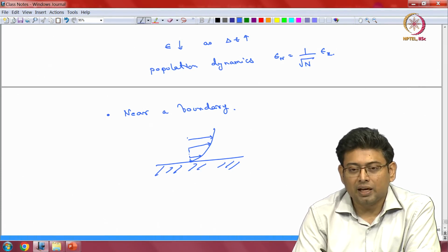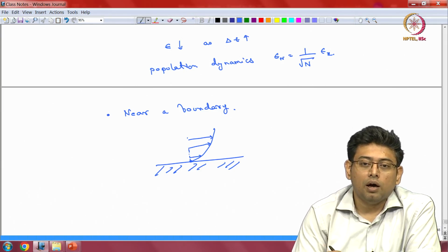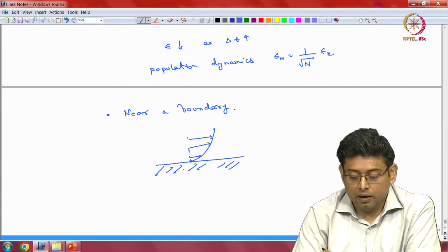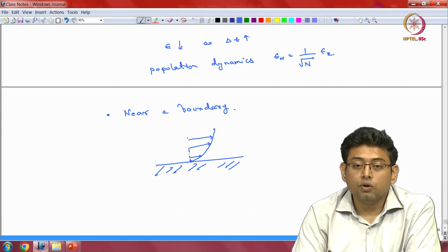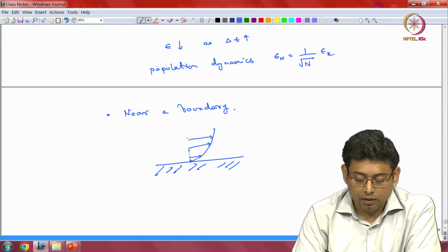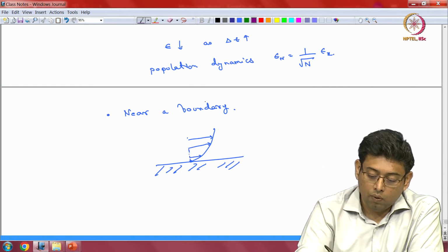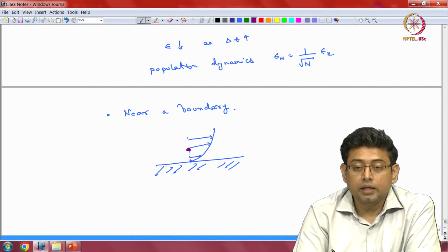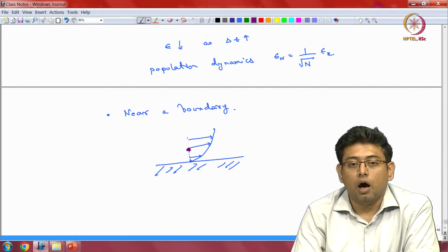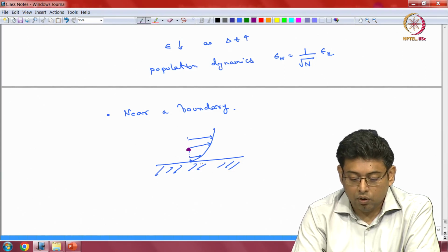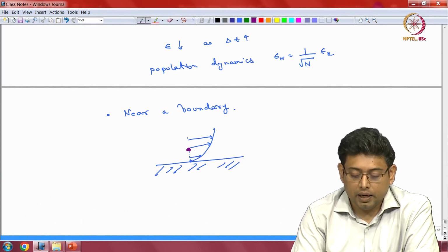This condition can be violated under certain cases. You can have slip, for example, in nanochannels, or if the flow is very sparse, and there are some other cases, but the no slip condition is a very common case in continuum flows, and that is usually almost always used. So under this condition, a particle near a wall can experience certain specific attractive forces. If the wall is charged and the particle is charged, you can have short range attractive forces there, etc.